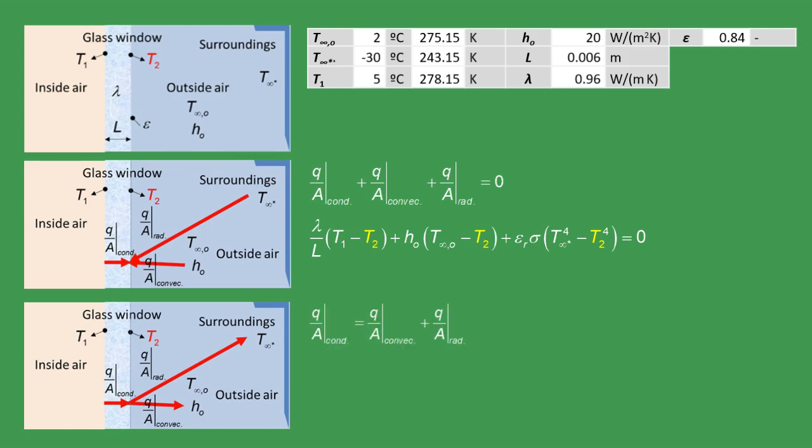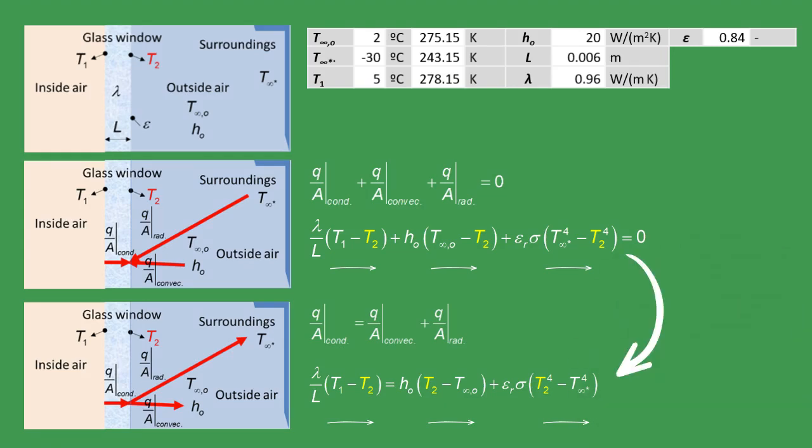In this model, the conduction heat flux equals the sum of the convection heat flux and the radiation heat flux. Take into account that this is only a hypothesis or a way of writing the conservation equation and the difference of temperatures. Therefore, like in the previous case, some components will be positive and others negative. Note you must write temperature differences in the direction of the arrows in the figure, as inputs or as outputs. Note that both sign criteria will lead to the same equation.